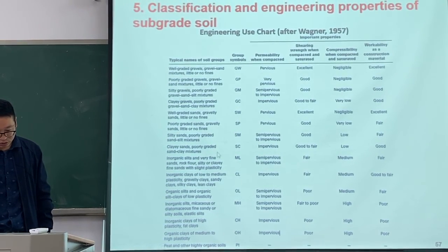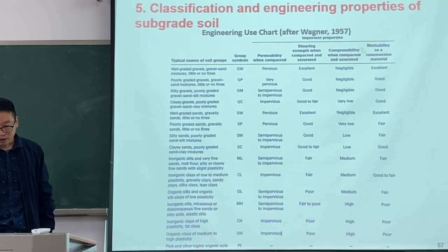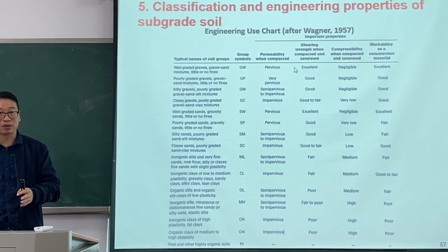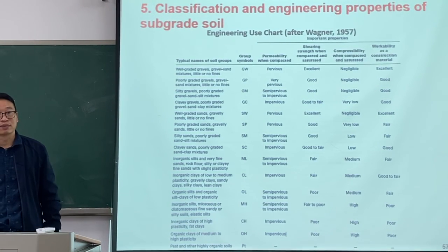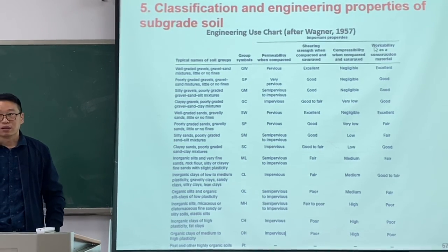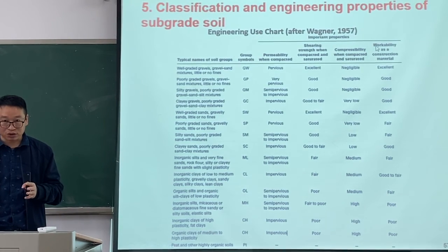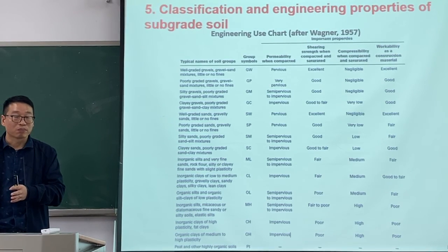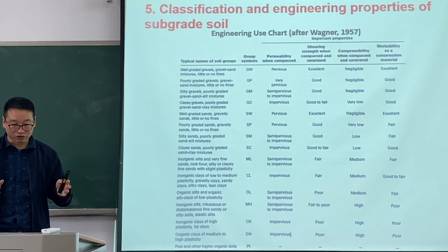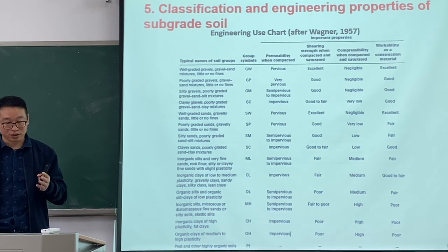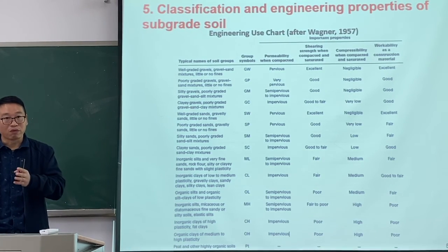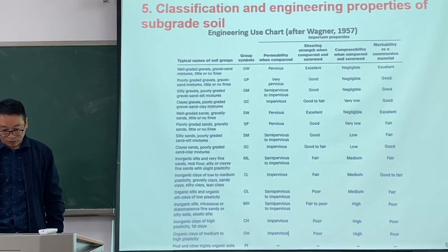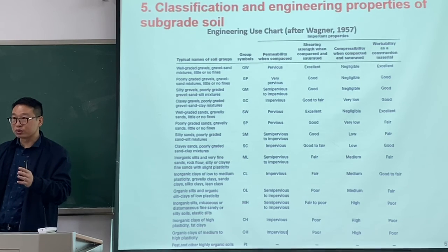According to the soil groups, we determine how to use them to fill the subgrade. Some soils are not able to fill subgrade, but some of them are good or excellent for fill subgrade. So we should determine which group the soil belongs to.